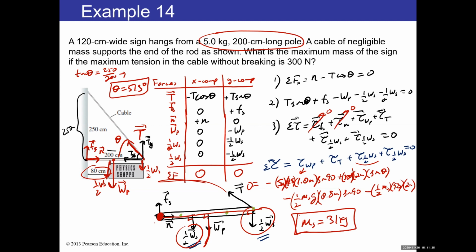This is how you solve this type of problem. You first do your free body diagram, then your force table, then set up the equations for the net force in X and Y. If you can solve for whatever you want from those two equations, fine. If not, include the third equation, which is for the net torque. Sometimes starting with the net torque equation is easier, and you might be able to solve for the unknown directly from there.